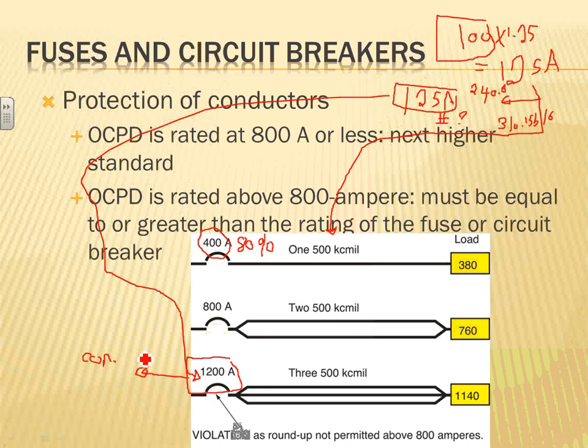Any comments, guys, about the 80%? Any comments about the 80%? That's the confusing part. Like I said, a lot of us even don't like to do this when we size the conductors. I don't know about you guys. We size the conductors based on 3 factors, and you choose the largest conductor. You have to be aware of that. Factor number 1, of course, if your load is continuous load, 1.25 times the load, size your branch circuit, service conductors, or feeders. Then you came up with size 1.